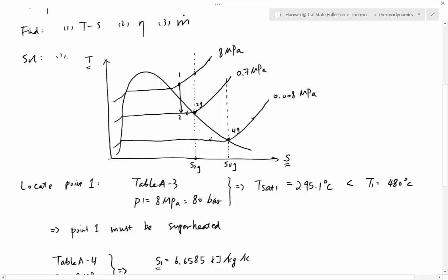So now what you need to find is S3 and S4G. If S3 is less than S4G, you must put number 3 to the left side of this reference line. If S3 is equal to S4G, then you must put number 3 right on this reference line. And if S3 is bigger than S4G, you must put number 3 to the right side of this reference line.